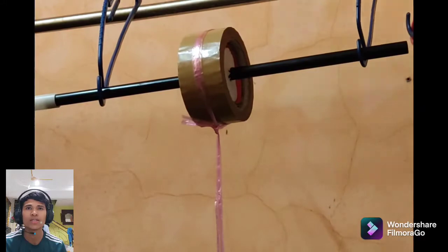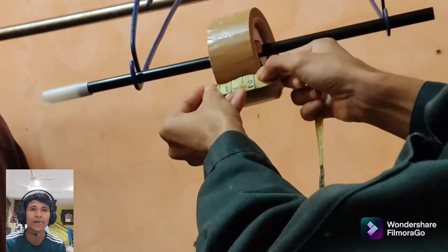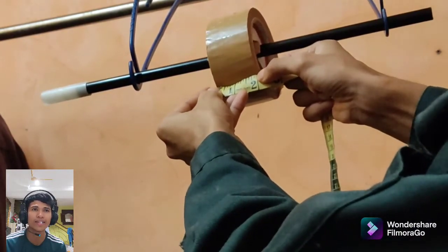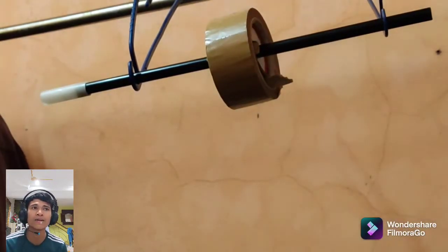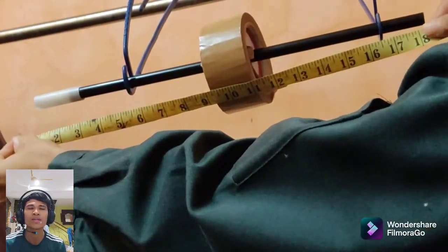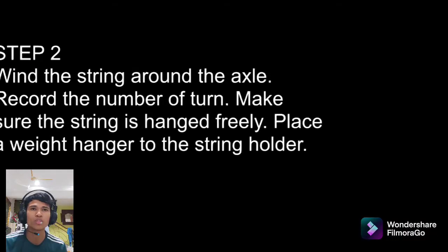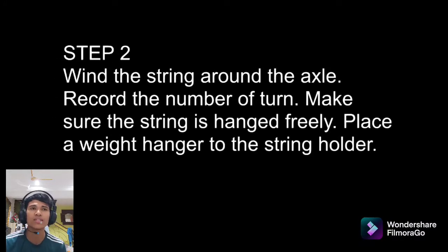The third step is to suspend 0.4 kg of load, which is m, on the string and take the time after releasing the mass from rest until it reaches the minimum point. And then repeat step 2 and also step 3 and get the average readings. Record the result into the table. Repeat steps 1, 2 and also 3 with every 0.4 kg increment until 2 kg.